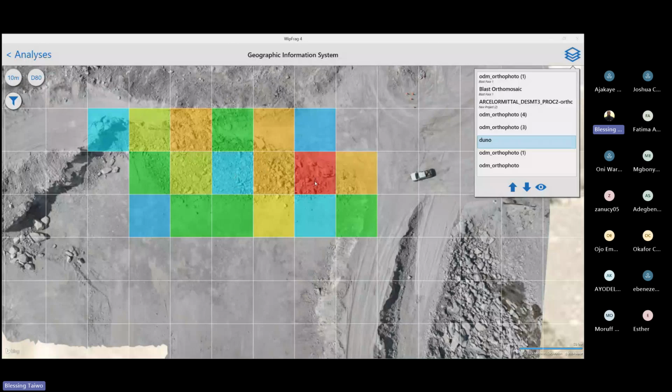If it is that case, then another thing could be that there is a fracture, a discontinuity on the wall that supports the escape of the explosive energy, and the explosive is now producing more boulder in this portion. You want to give consideration to that part. It could also be that you have a misfire, blowout, cuts in your detonation cord, or maybe the explosive is deflagrating at this point. So you want to investigate. So the software gives you information on how to do that.